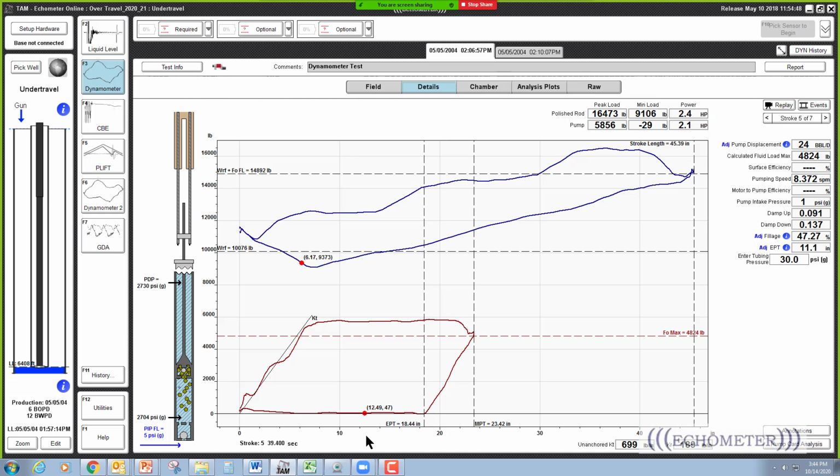Yeah, 18.5, 18.6 inches. And so the surface stroke is 45.4, and the pump stroke is 18. And there's also, you're losing this much of the stretch from to right there. You're losing that much of the surface stroke to tubing movement, which is about 6 inches of loss due to the tubing movement.